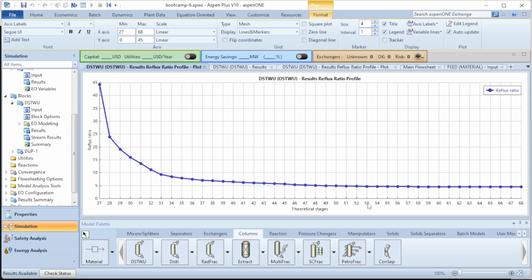And in a sense, the condenser duty that needs to cool the product in the distillate stream to send back to the reflux tank, to the column, has to be higher. The reboiler duties will also increase, since more liquid is being dropped into it, more will go to the bottom and needs to be reboiled and sent back into the column.